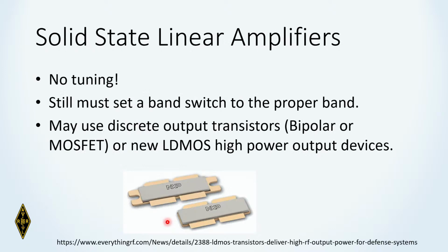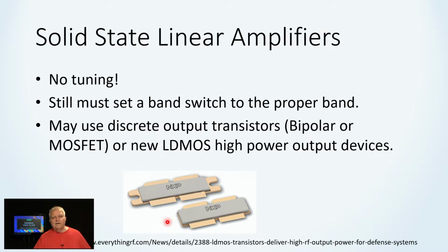Now, if you have a solid state amplifier like myself, the beauty is you don't have to do any tuning. You don't have to do the plate dip. You don't have to do the load for max. But you do have to have band switching going on. And most amplifiers will be able to read the frequency from your radio and do that for you.